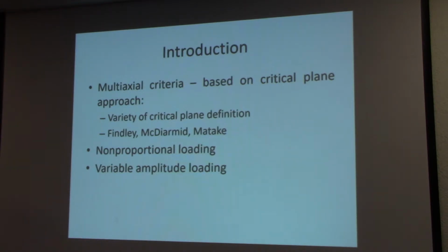Okay. So about multiaxial criteria, nowadays the most commonly used criteria, as I can see in the literature and in usage, are the critical plane approach. Of course, there are multiple other criteria, so I will be dealing with three of them, specifically Findley, McDiarmid, and Matake, and I will explain why I chose these three particularly.